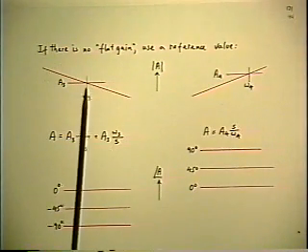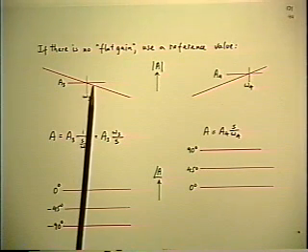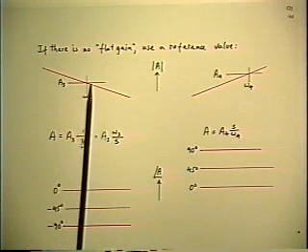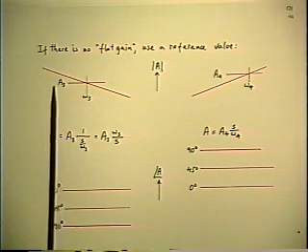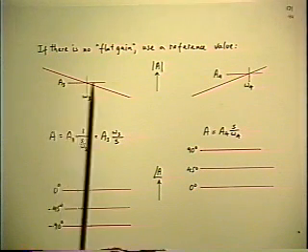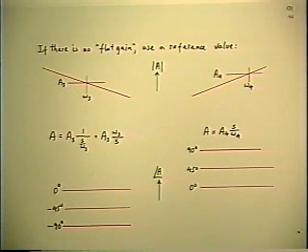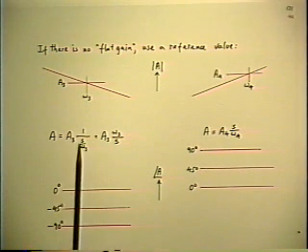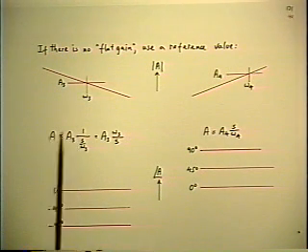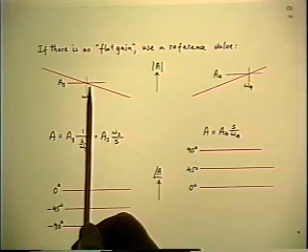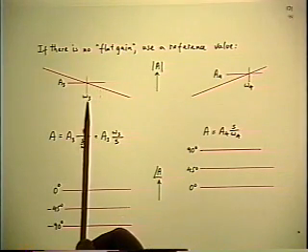So what you do is you just take some arbitrary point on the asymptote, which has a corresponding pair of values of a frequency and the gain at that frequency. And the expression that goes with it is A equals A3 at the frequency omega 3.